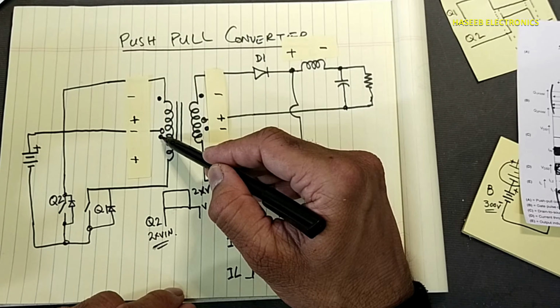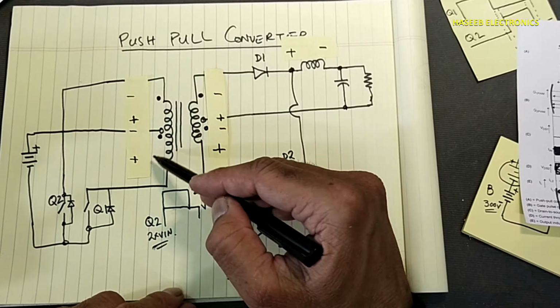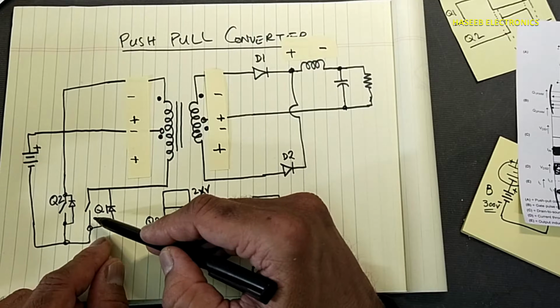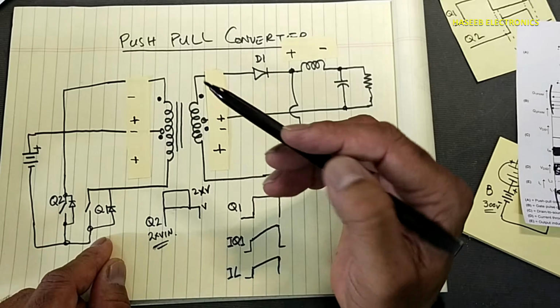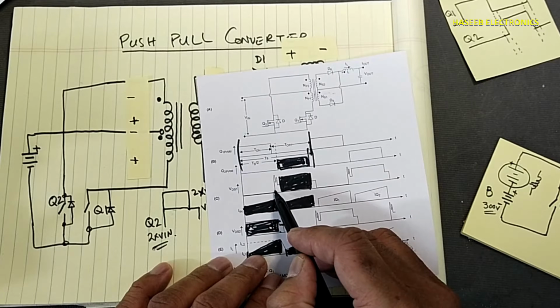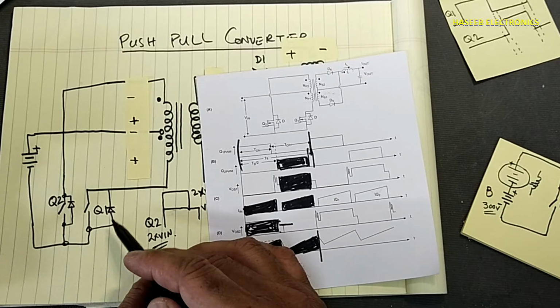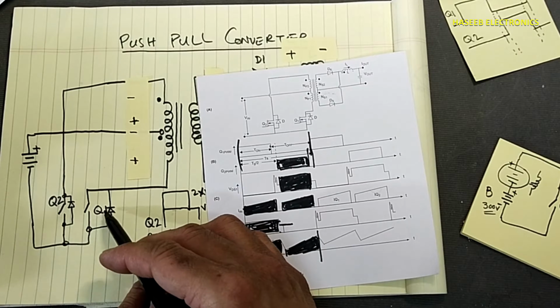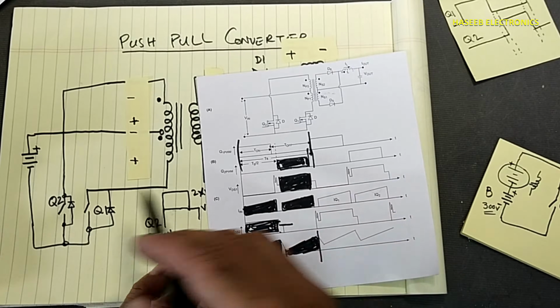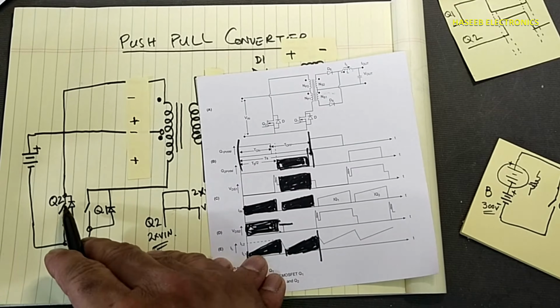And the same double voltage stress, positive, negative, positive, double the applied voltage, will be on Q1. This is the dead time when Q1 is turned off. After that, when its magnetic field collapses, it will produce a spike, so that will be discharged by Q2.